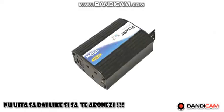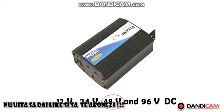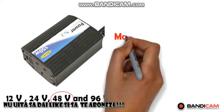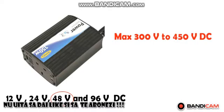Similarly, inverters are also classified based on the input that they accept. That is, they can accept 12 volt DC, 24 volt DC, 48 or even 96 volt DC. Note that 48 volt DC input is the most common type of inverter used for residential solar PV systems, while 12 volt DC input inverters are more commonly used in portable applications. Power inverters in solar farm can also have input voltages from 300 volt DC to 450 volt DC.